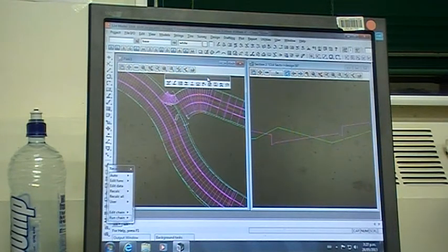Now, the same network editor that we're about to open does both of them. The first time that we run it, we always use a rational formula, and this allows us to size the pipes. Okay, so based on all those things that you know from your hydraulics, you need for your flow under the rational formula, you need a catchment coefficient or a percentage of impervious area.